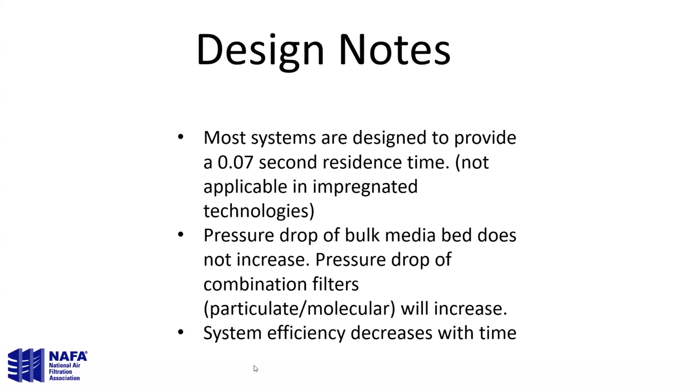Pressure drop of bulk media beds, they don't increase, provided they're protected. I say this often, and a lot of times people come back and say, well, the pressure drop went up. Well, if you don't put a particulate filter in front of your carbon bed, and a lot of dust gets on the carbon in front of this tray or on this filter, your pressure drop will increase, but not because the carbon is being loaded.